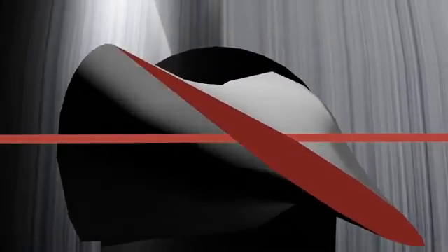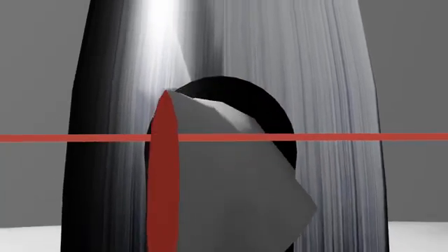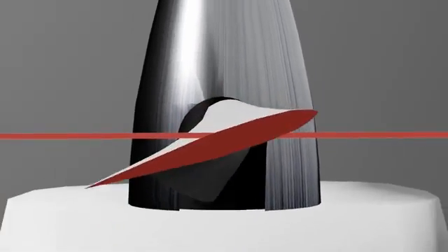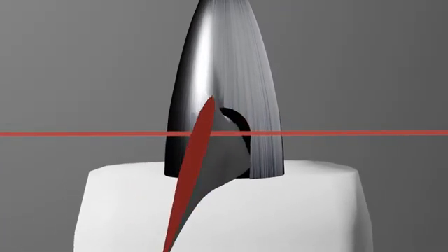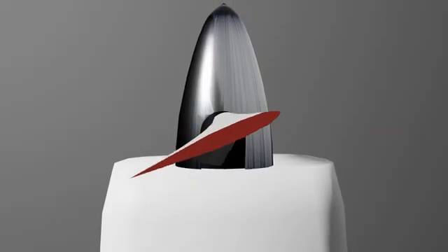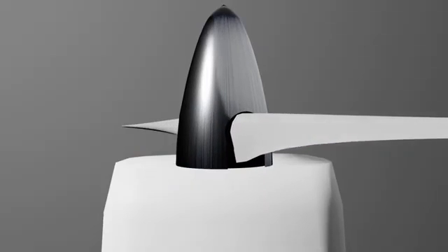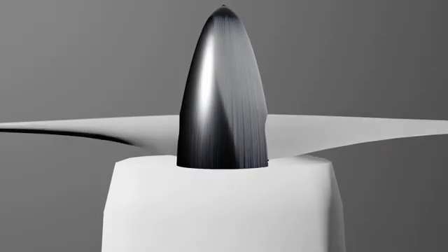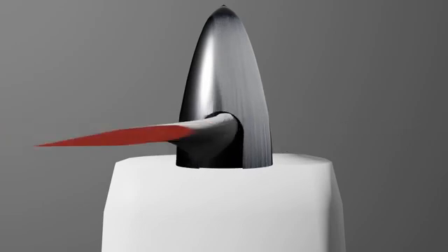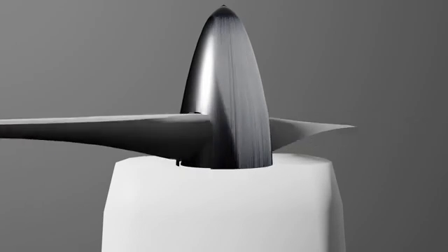How can we control the blade's angle of attack? Well, on a propeller, it's called its pitch. On modern constant speed propeller applications, this pitch is automatically adjusted by a governor. The governor's job is to govern or maintain the RPM. It does this by balancing the forces trying to spin the propeller, called torques.